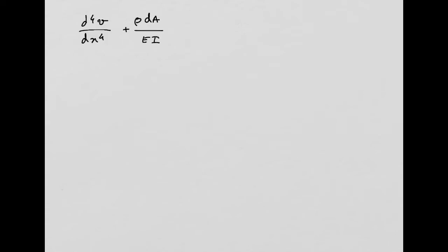EI, so I'm just writing what we derived last week, now a second derivative in order to time, equal to 0, because we were considering free vibrations, not forced vibrations. So we are looking for the natural frequencies of the beam.